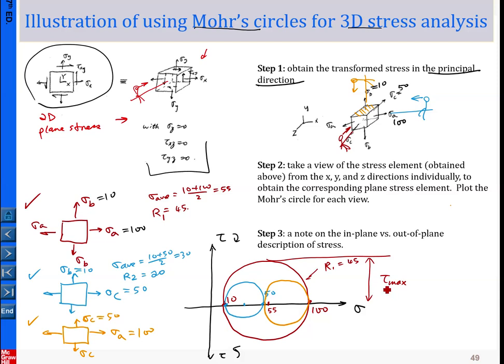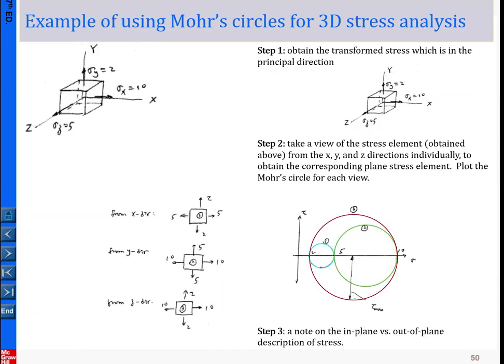Okay, and such a maximum shear stress will occur in such an orientation, in such a transformation, looking from this viewpoint. So if you look at this element projecting in front of you, then the maximum shear stress will occur by rotating. Let me move out this one not to mess up the drawing. So that will be the rotating in this sense. Okay, so in terms of three-dimensional, that could be something like this one here. So that is the application of this kind of Mohr circles.